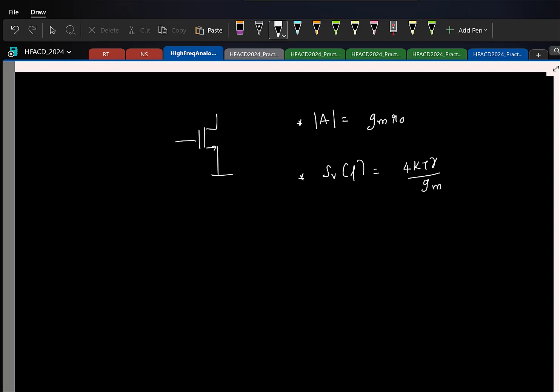So from here, what is the solution? What should I do? I have to double the GM. Again, the way to double the GM without affecting the operating point voltages is what? It's like you put 2 transistors in parallel, right? We have already seen this during characterization things. If you put 2 of them in parallel like this, GM doubles, and total power also. What can you say about the current if this is I0? The total drain current is 2 times I0.